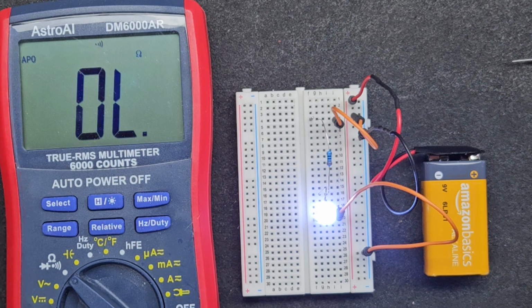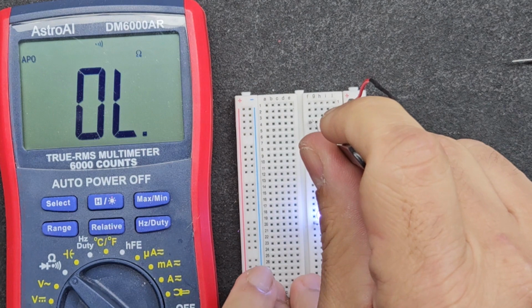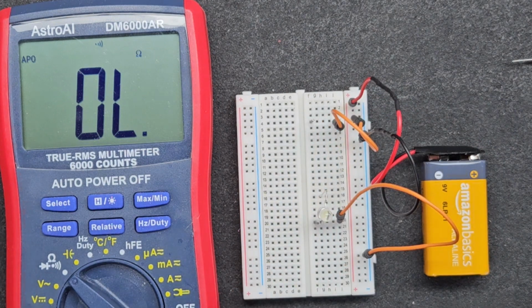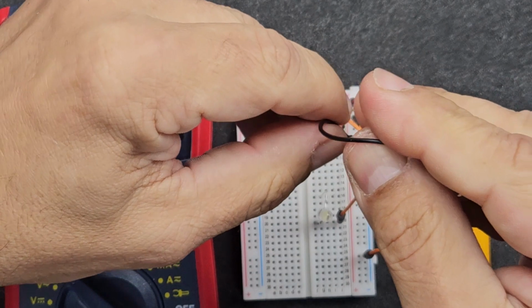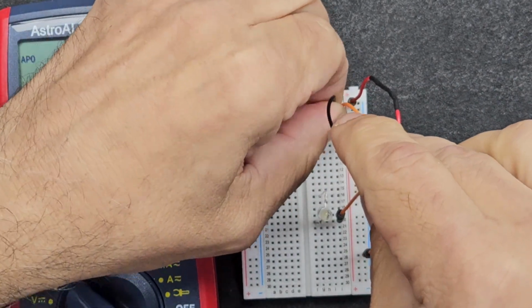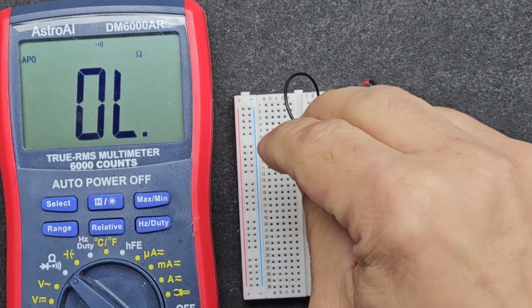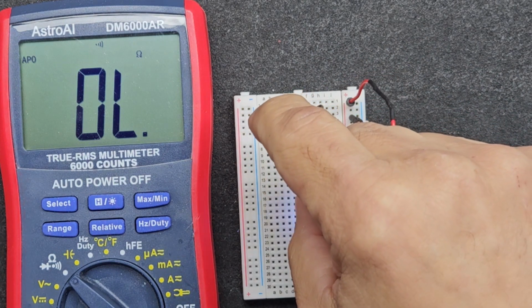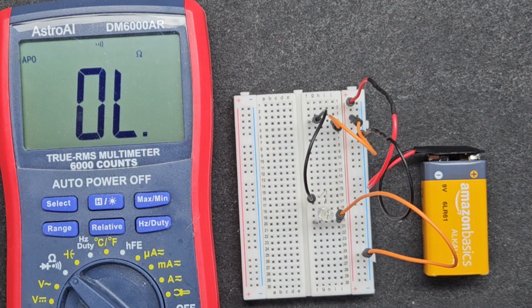Now what we said, this is a 3 volt LED. What if we add 9 volts to it? How long will it last? Let's find out. So what we'll do is we'll remove the resistor. And let's add another jumper cable. So we'll go positive. So you saw that? Sorry about that, my hand was in the way, but you may have seen a small flash of light. So what happened was the LED lit up and instantaneously blew due to the overload, right? Adding 9 volts to it is going to cause the LED to blow.